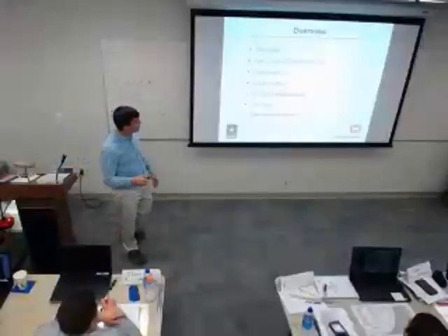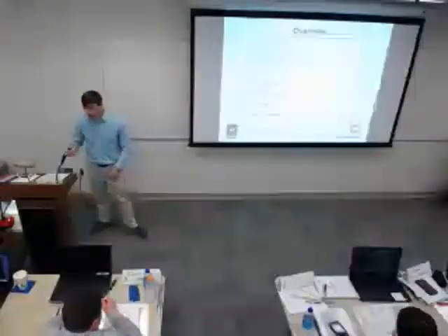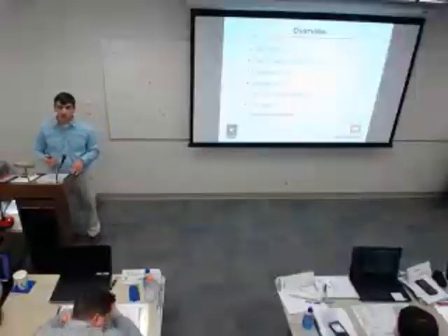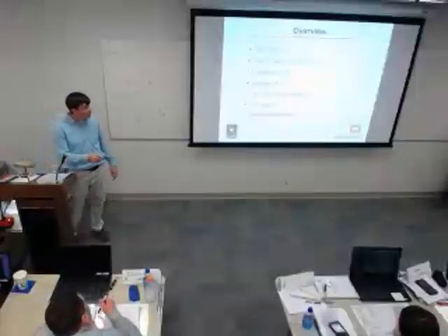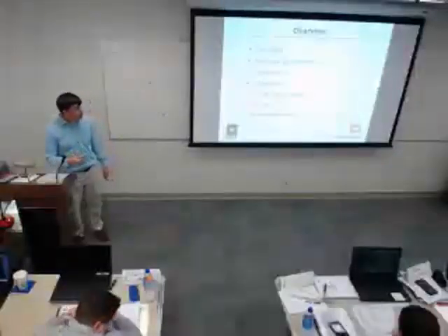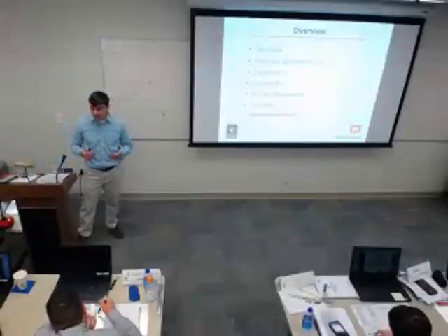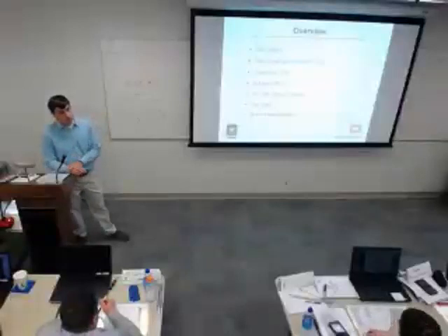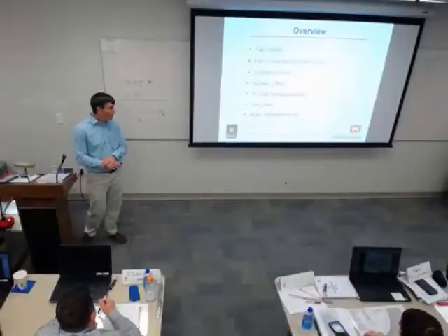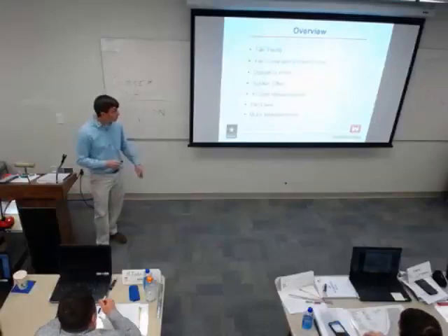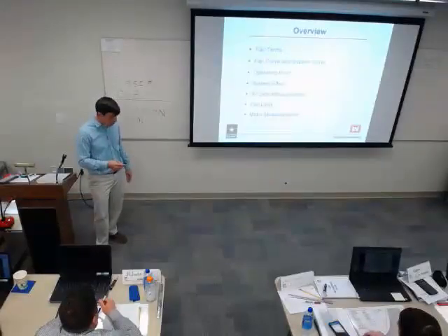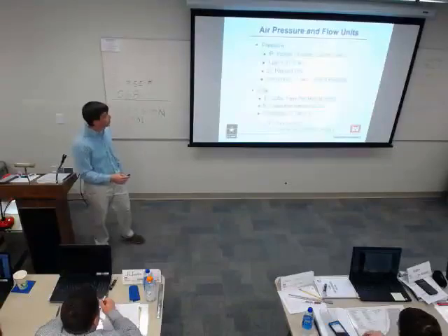We're going to talk about system effect, which is a phenomenon where you have some unexpected losses in your system. This is really more for the design guys in here. They might need to consider it. And for the field guys, if you've got a fan that's not moving the airflow you think it should, you might want to take a look at system effect. Again, airside measurements, the tools used to do them, fan laws, and motor measurements. Talked about those a minute ago.